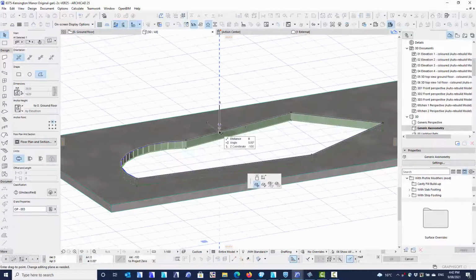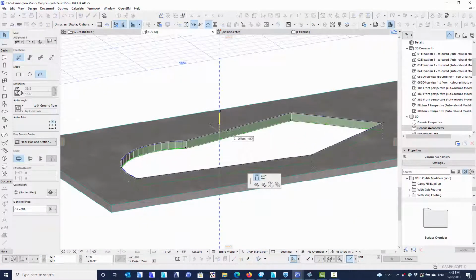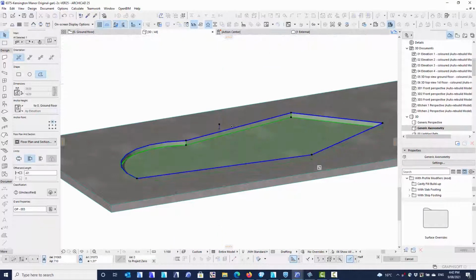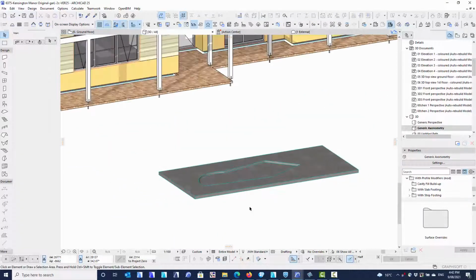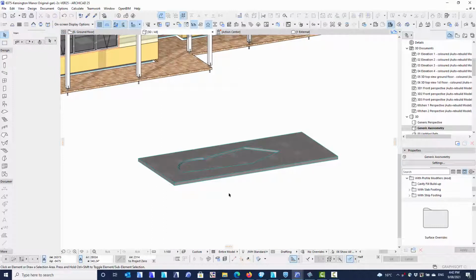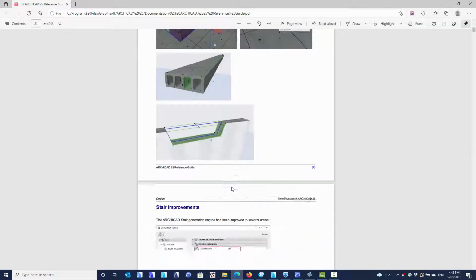And this is the great thing about openings, I can now adjust the height of that thickness, so I can pull that up to about there, so I can make a nice little niche, if you like, in that slab. You can do this, of course, in slabs, walls, meshes, beams. We can add openings to them, and you can manipulate their size and depth, so now we can have polygon openings. So let's go back into our documentation.